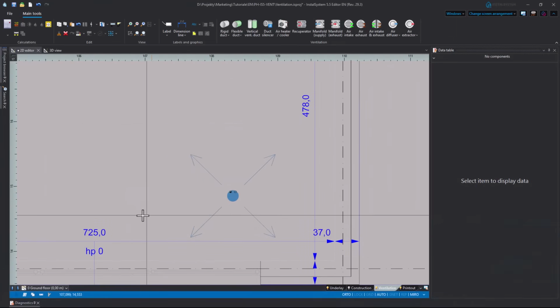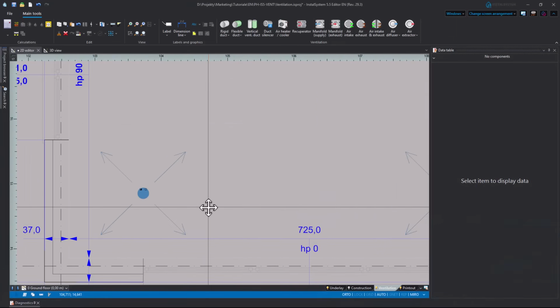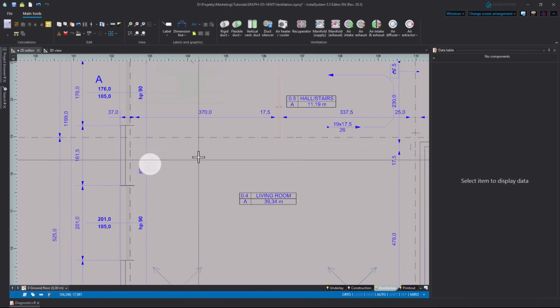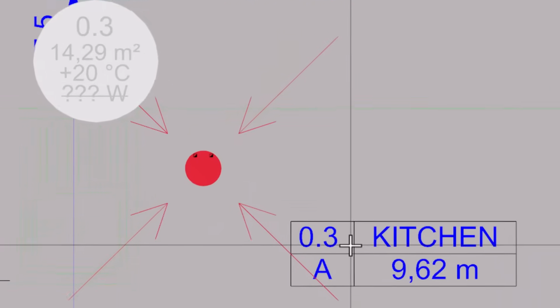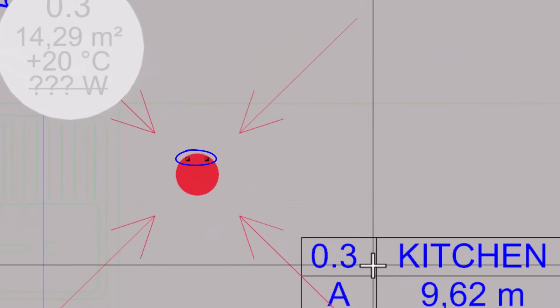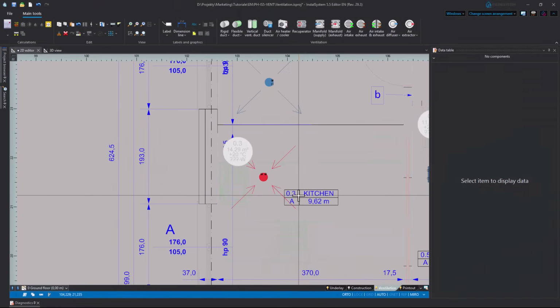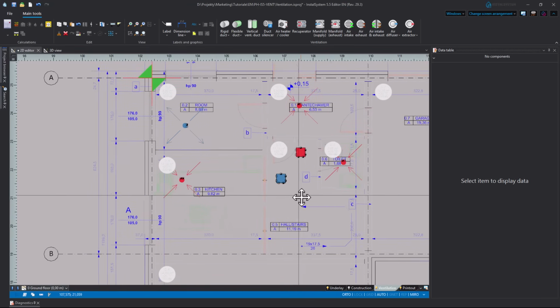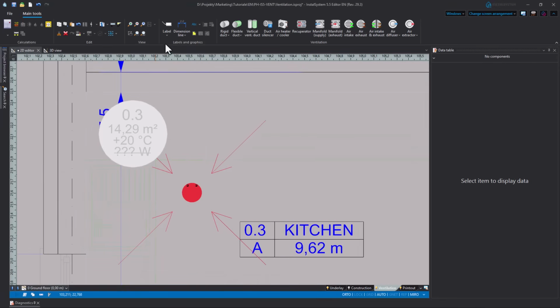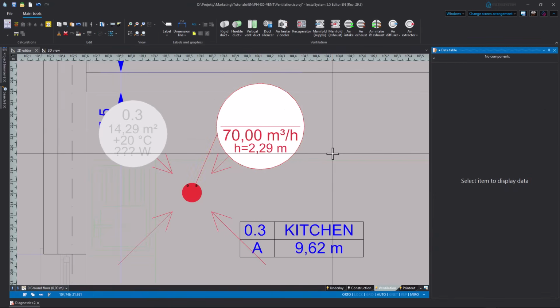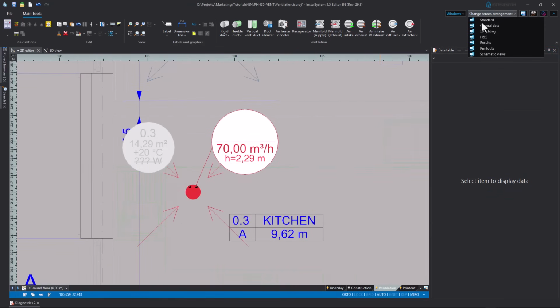If the boxes with the ability to connect multiple ducts have been used, a quick glance at the drawing will let you know how many ducts should be connected to a given element. Connected points are indicated by a half-solid square. This information can also be displayed in the air diffuser or air extractor label after label contents modification.